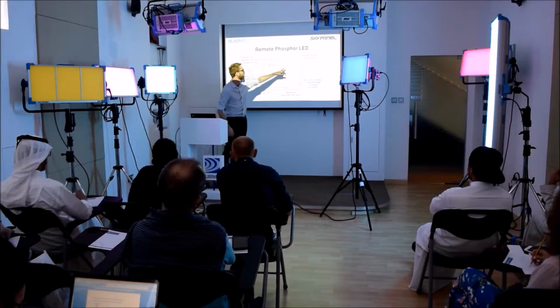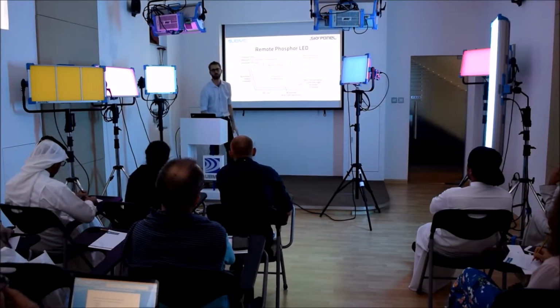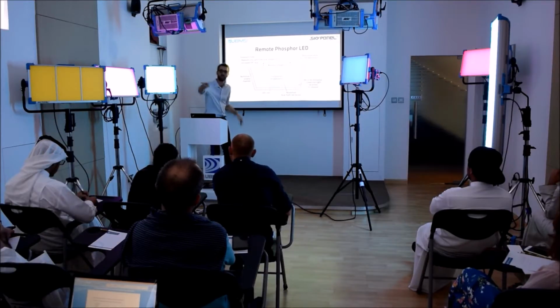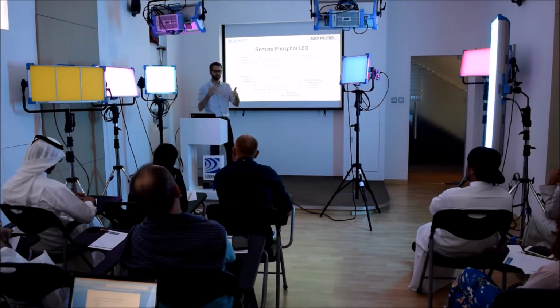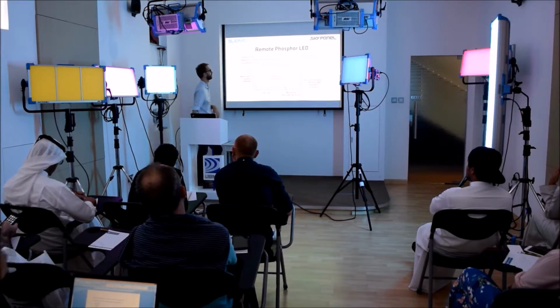It's exciting the phosphor in the remote panel, and we get a maximum full spectrum white light being released from the phosphor panel. So the light that we actually see is being emitted from the phosphor panel itself, not from the LEDs behind it. The LEDs behind it, all of that energy is getting absorbed and re-emitted from the phosphor panel.